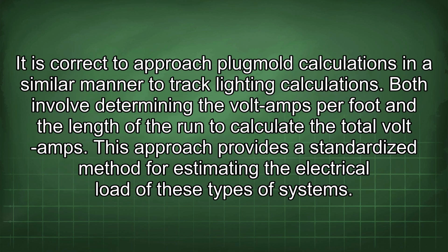It is correct to approach Plugmold calculations in a similar manner to track lighting calculations. Both involve determining the volt-amps per foot and the length of the run to calculate the total volt-amps. This approach provides a standardized method for estimating the electrical load of these types of systems.